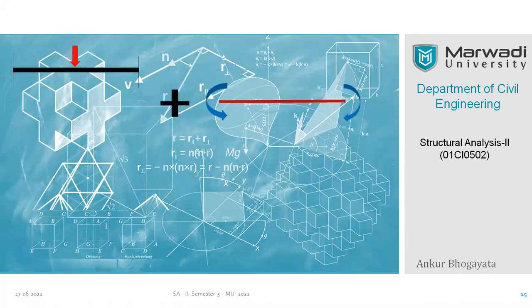That's a fixed beam with a point load. So first of all, I have removed the end moments. So it becomes my simply supported beam like this. And plus, now you can see that I have only applied the end moments on this beam. Okay. So when you now club them together, it becomes ultimately your figure number one.